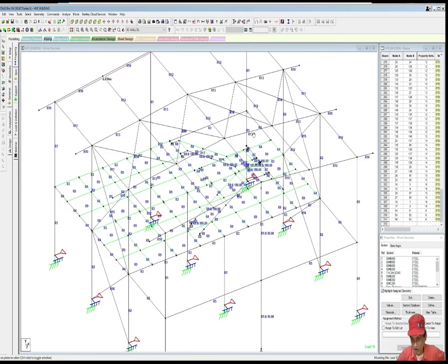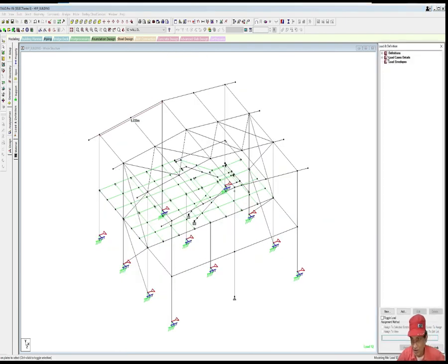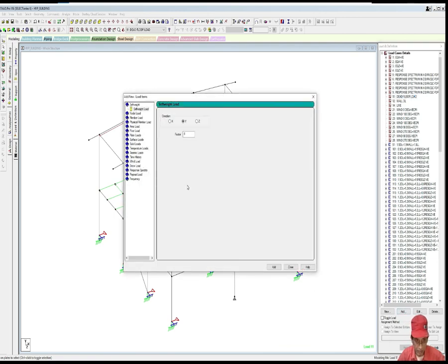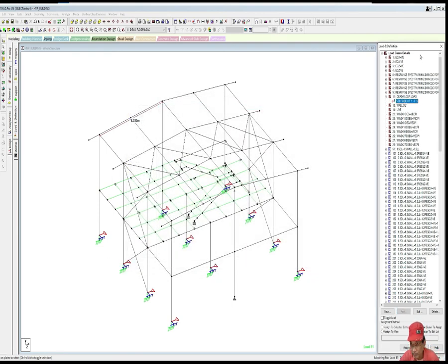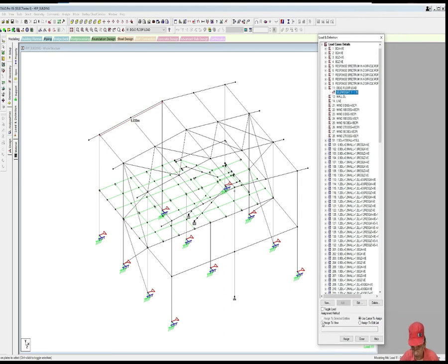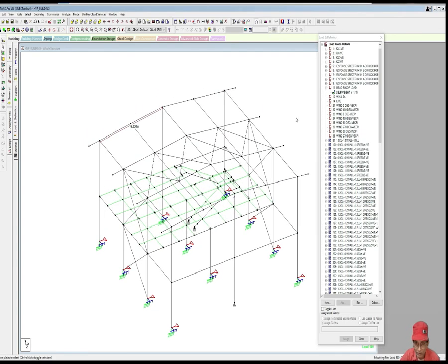So we have to now give it a run with the self weight. Let us go to load and definition. From the template we already have dead load. We usually assign 15% more dead load for bolted connections. So self weight will be 0, -1.15. Add, assign to view. Okay, it has been assigned.